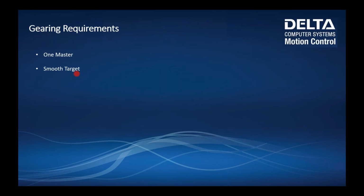If you've got two axes, they start from the same position and you want them to end at the same position, you can issue them the same move absolute command at the same time, and that'll give them both the same target. So they are synchronized together, but you don't really need to go through the gearing process for something like that. Where gearing really shines is where you've got a relationship that isn't just one-to-one. Maybe it's something slightly different. And we'll see how that looks here in just a second.